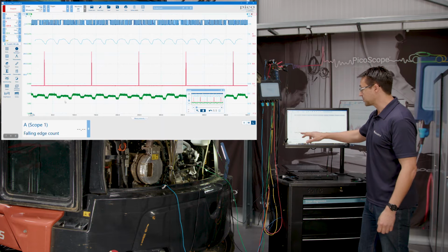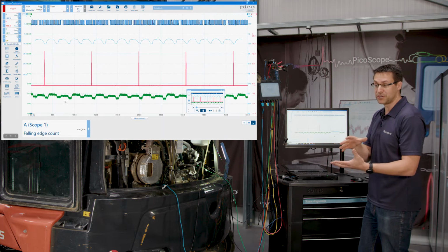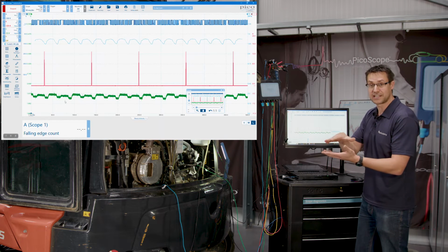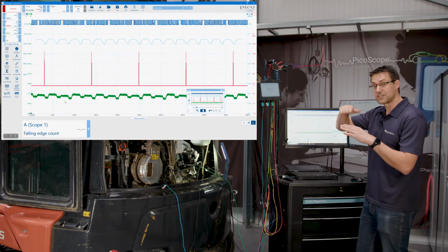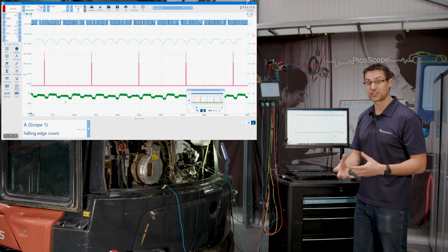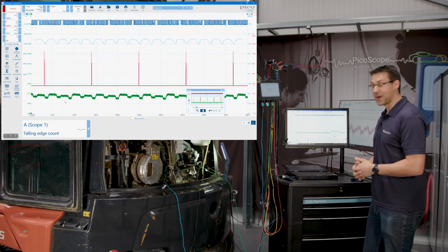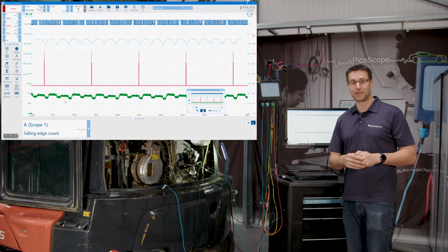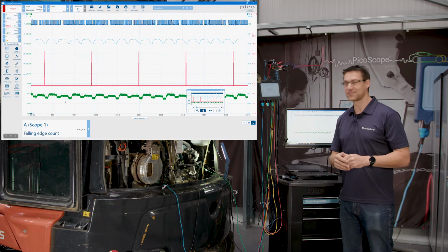Too, in the rail pressure sensor, if pressure can't release, it's just going to stay static in the rail. Therefore, we'd get a slight build-up in pressure as opposed to it dropping after each injection event. Right, that was a very quick introduction to a lot of things. I hope some of it makes sense.